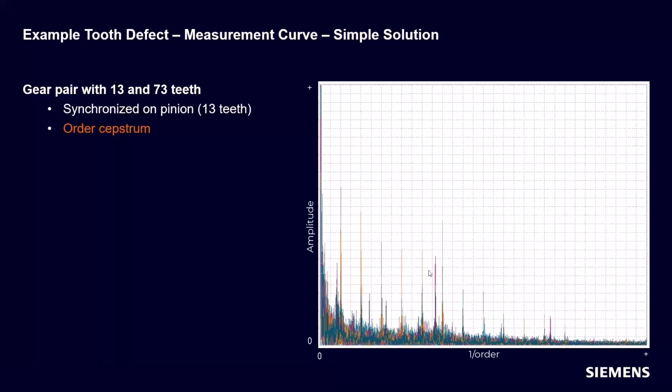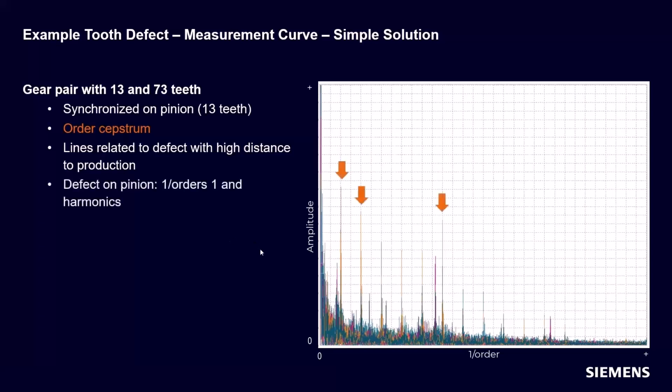And we see at a point which is again 1 divided by 0.178, which shows us exactly the origin as the gear. Here we are able to distinguish the quite single lines, or only a handful of lines that are affected by a certain defect. So if you look back at the order spectrum, then, for example, the energy that is now concentrated on those two lines was spread over many, many lines. But if you look at those two lines, we are really able to calculate a metric with a high reliability that we can use in the production line.